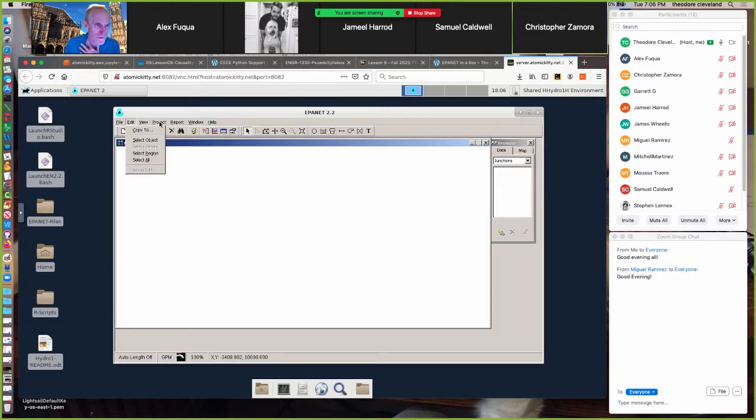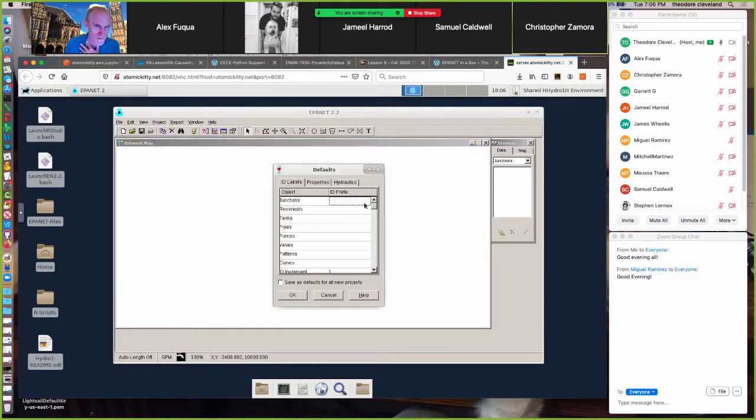So the first thing we're going to do is go to the project window, and I'm going to set defaults. Go into hydraulics, and for our first problem I'm going to put it into cubic feet per second, because we've done that exact problem earlier in the class on the online calculator, and I believe the answer is somewhere around 11 or 12 cubic feet per second for that problem. And let's switch to Darcy-Weisbach for our head loss formula.